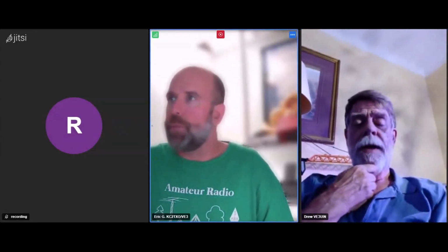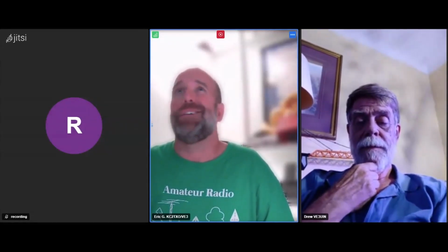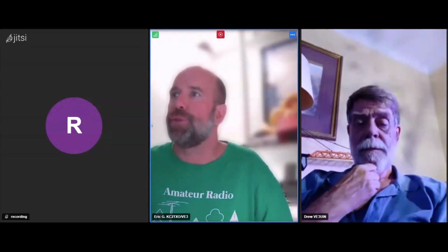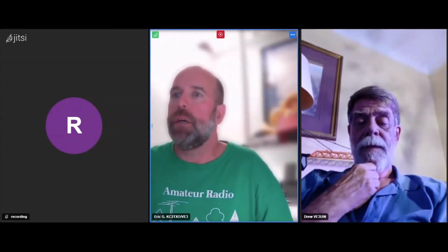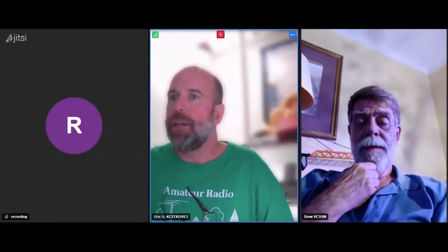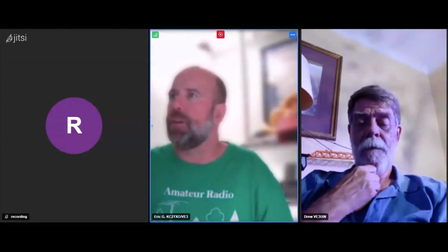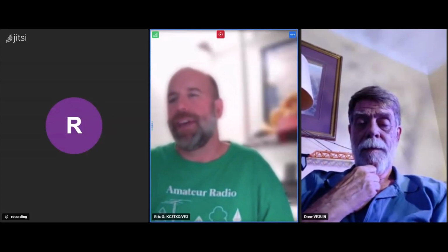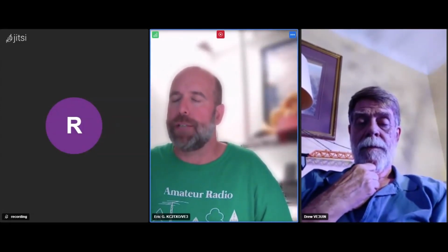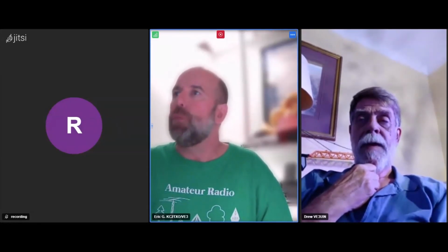You can sweep any frequency you want at any resolution, and I think it was hovering around 6 megs or so when we were trying to tune for 40, and it didn't matter how much we shortened it. We shortened it by a foot, 2 feet, and it was barely budging, where you're supposed to do minimal changes. The way we were shortening it, we realized afterwards, is that you're supposed to bend it back and wrap it around itself. We were just kind of coiling it.